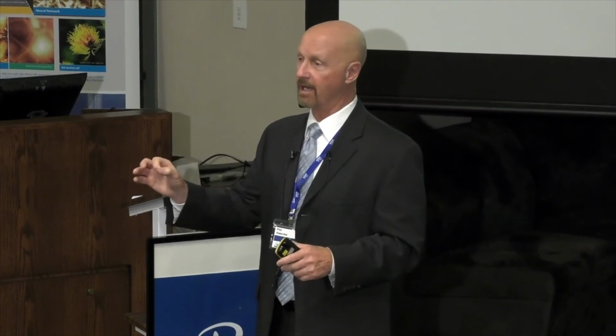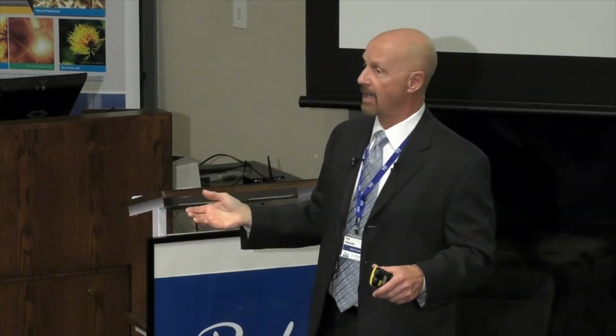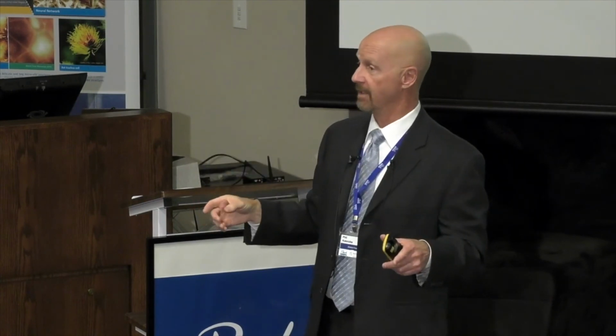And again, on one data point, you may take a quick look at it because you're not digging too deeply into a manufacturing process, but you can say, well, okay, this might be something I need to keep an eye on. This is especially problematic with rapid thermal processing now, where your anneals, taking up to hundreds and close to 1,000 degrees C, happen just over a few minutes rather than hours. Rapid thermal processing tends to cause defects in silicon because of thermal gradients.